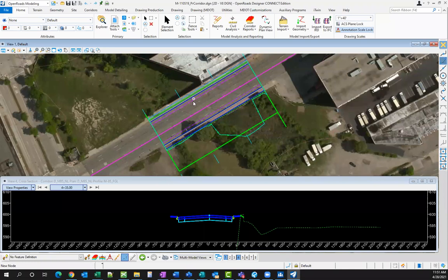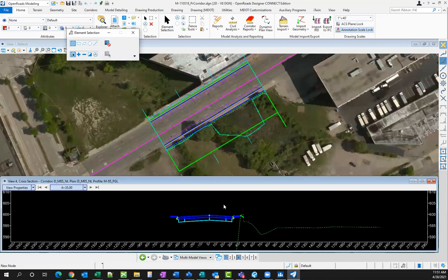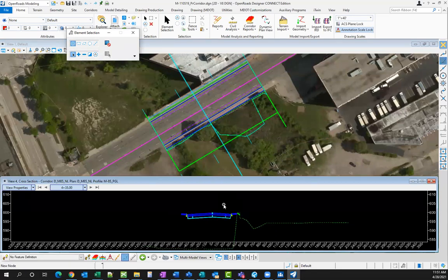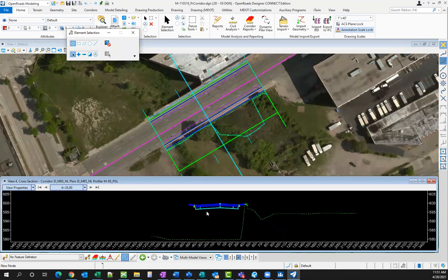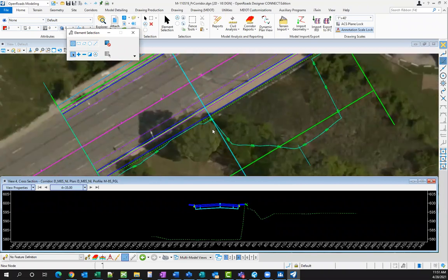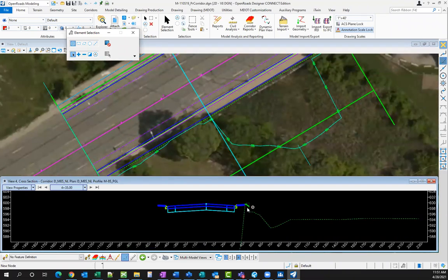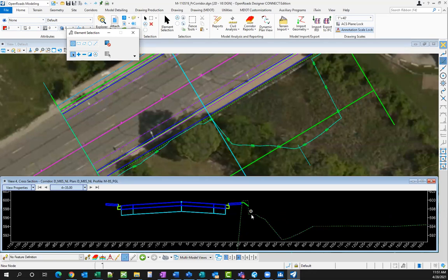So basically this old railroad line, it was abandoned. The railroad company had no vested interest in it. So basically like 20 feet of fill to fill in this roadway. And the cross section that I'm looking at down here, you can see this is basically where the bridge used to be. I don't have all of my end conditions shown here, but we're filling this whole area in with dirt instead of a bridge. And at the specific cross section that I am at, in this case, you can see my end condition. This is actually the old bridge barrier wall.